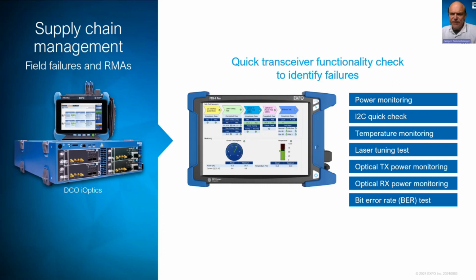Then for the processing of the transceiver, the bit error test here reports the count of the bit errors and also the pattern loss status. So here there are a couple of test setups applied. In detail, we have the nominal, the min power, then also the minimum bit rate, the maximum bit rate, as well as the measurement at the minimum and also the maximum wavelengths.